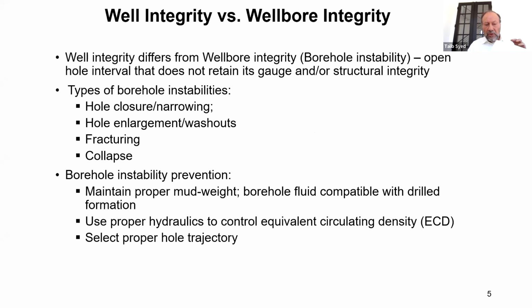I'm differentiating here between well integrity and wellbore integrity, because to me, wellbore integrity could include borehole instability. And that is when the open hole interval does not retain its gauge and/or structural integrity due to hole closure, narrowing, washouts, fracturing, collapse, etc. So what happens is mechanical borehole failure occurs when the stresses acting on the rock exceed the compressive or tensile strength of the rock.